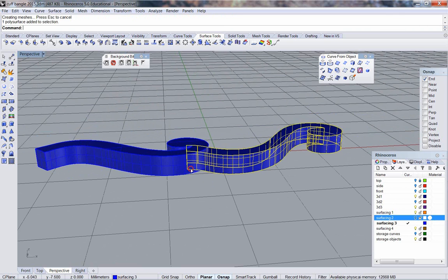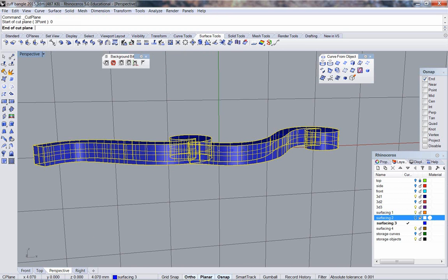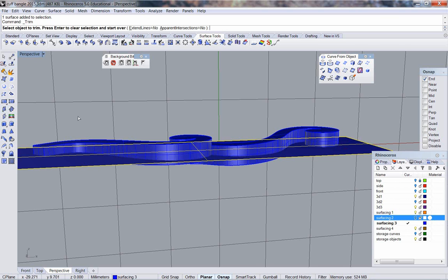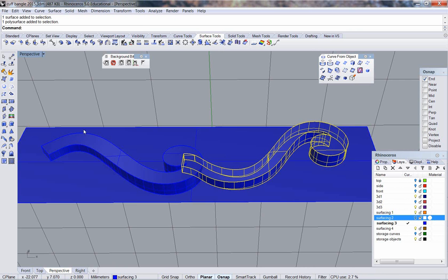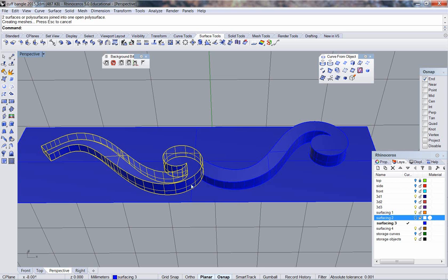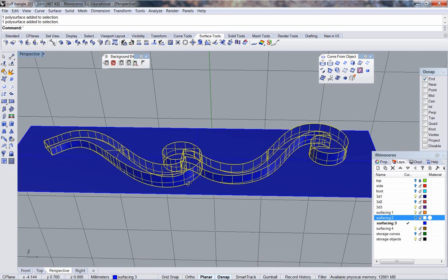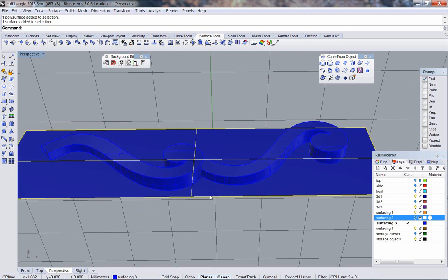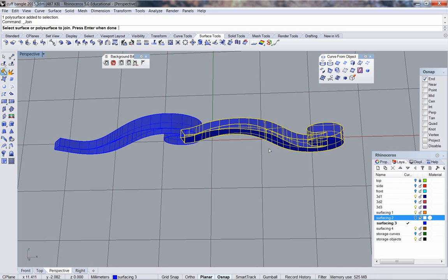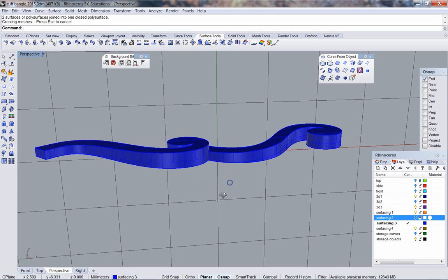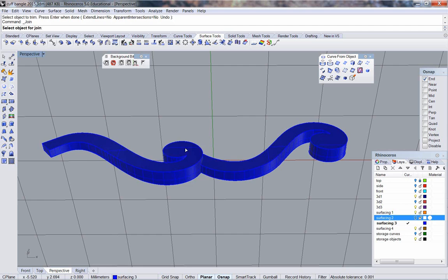That'll be fine. Go into my front C-plane, cutting plane, 0, enter, shift key, pull to one side, trim off the bottom. Join these together, join these together, use this to trim. I'll make a copy of this. Use this one to trim. I copied that to clipboard. Join these together. Paste that back in. Use this to trim. Join that together.